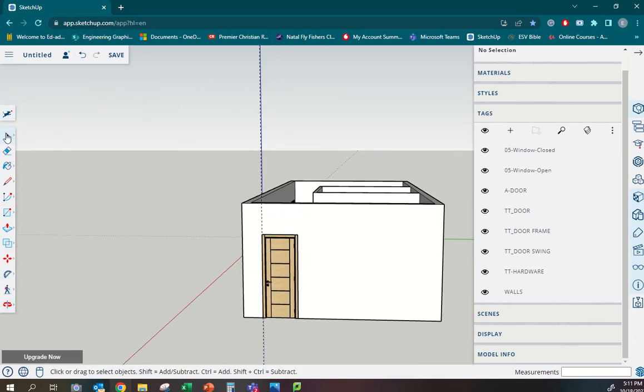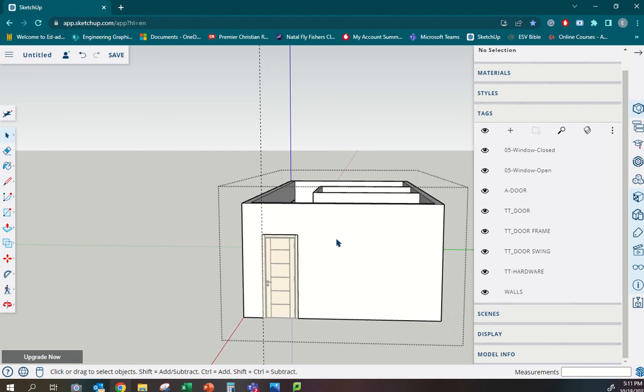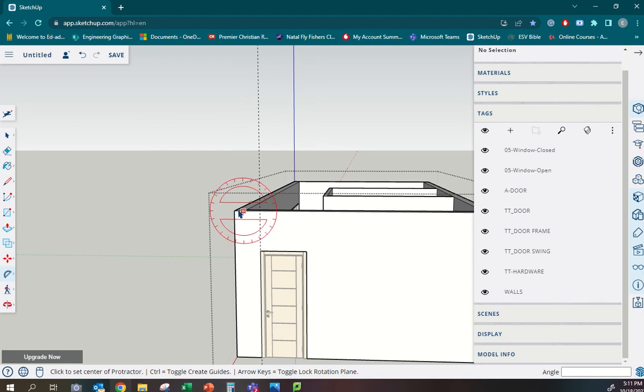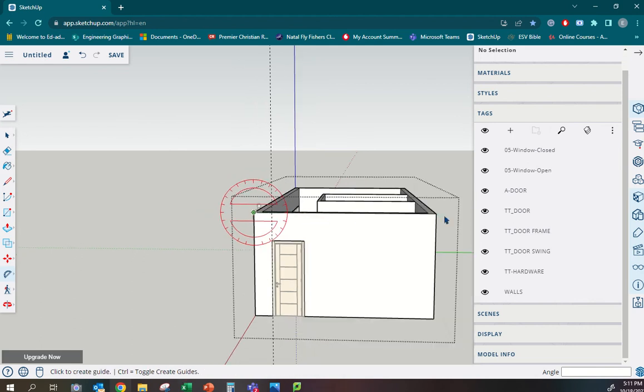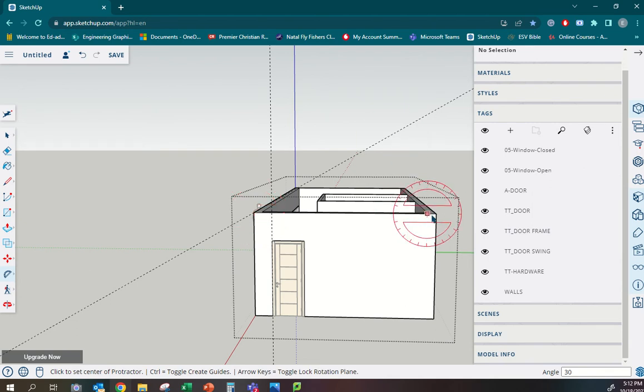So the first thing I need to do is click on the wall, because we're going to add volume to the wall. So to create that gable profile, I'm going to go to the outside edge of the wall, go to the other edge, and run a line up at 30 degrees. So I'm typing in 30 degrees at the bottom right hand corner of the page. You'll see the units I'm entering. Enter. It gives me that nice guideline. Click, click, move up 30.